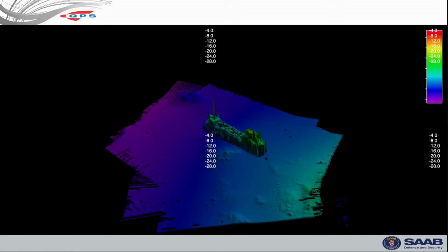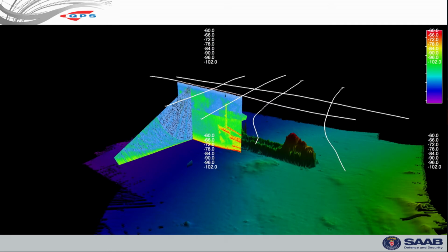Then I take this information, I go, okay, let me take this all together now. And I could take what I learned in the last two examples, expand those to see how much can be found within a single scene itself. So in hydrography itself, we began using the water column information, as mentioned, to look at the least depth. So what happens is when you're running a multi-beam system, you have 512 beams, for instance, and you have to choose where the data point is going to reside within each beam. And a lot of times that's not going to be the shallowest depth. So then we revert back to the water column information to start looking at it.